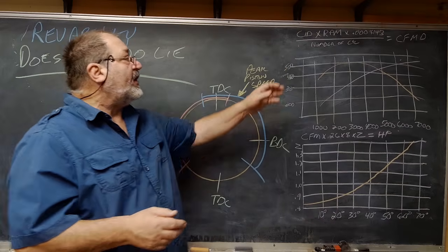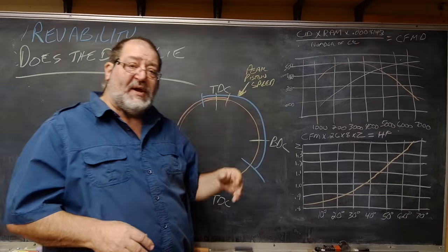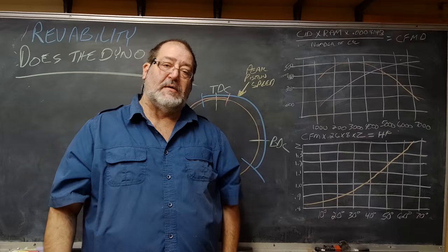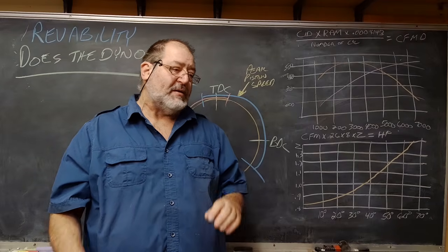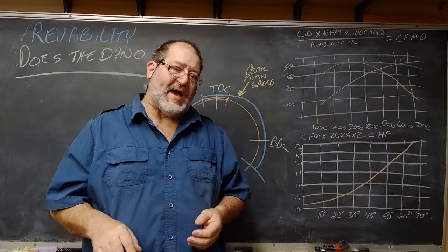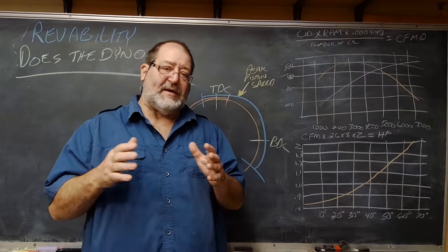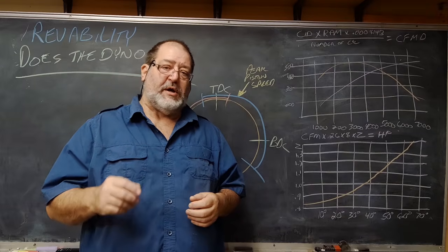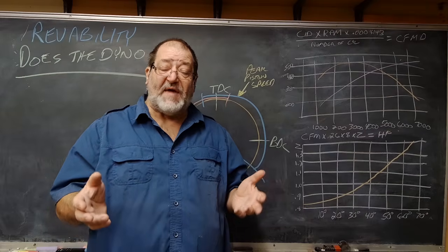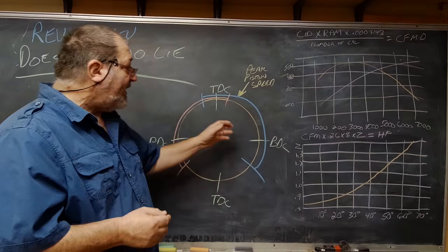If you start sizing things correctly, or you're limited because class rules say you have to run this head, that's all you've got. Even if you've tweaked it a little bit, shop peened it so they can't tell, it's still limited. That head can only do so much. You might have given it a better valve job. You might have picked up a few CFM. All of that helps. But what you're really stuck with is the camshaft.